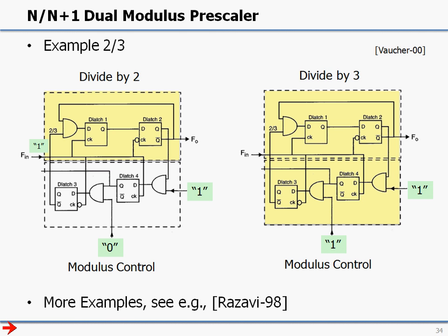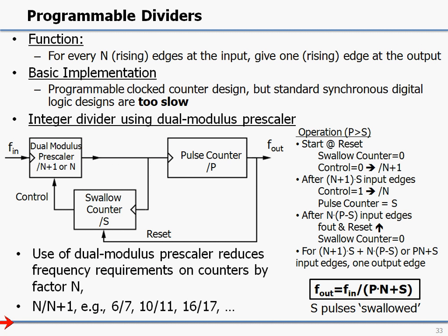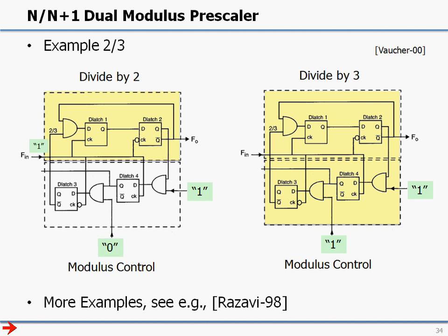Now, one thing to point out, let me maybe go back one slide. The advantage here is that these synchronous counters operate on average on a much lower frequency, and so overall, if we can design the prescaler as operating at fast frequencies, then we can reach higher operating frequencies than we can reach with the regular synchronous counters. Okay, let's quickly look at how this 2-3 circuit works.